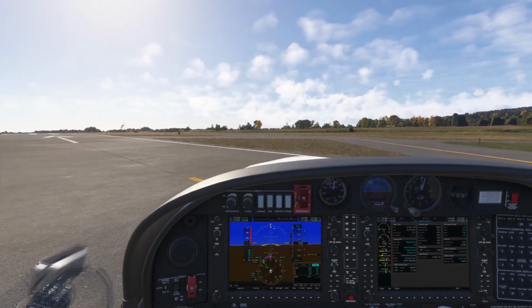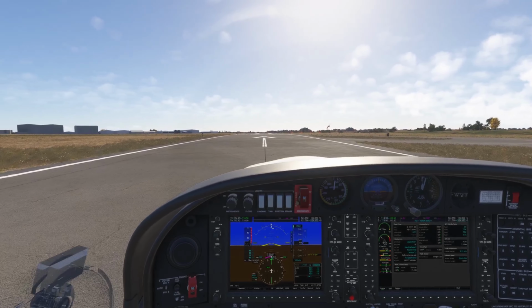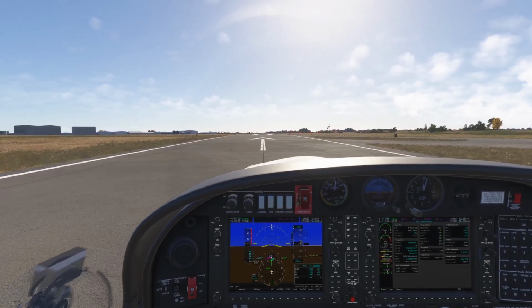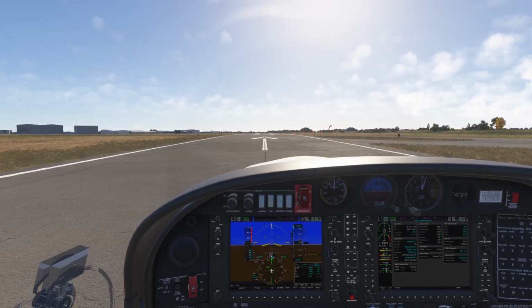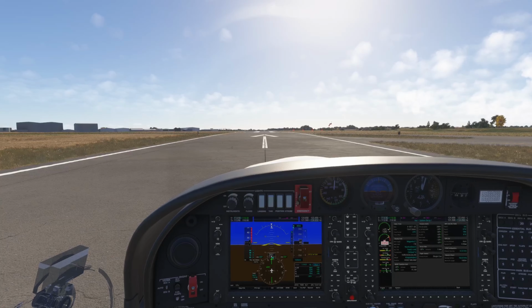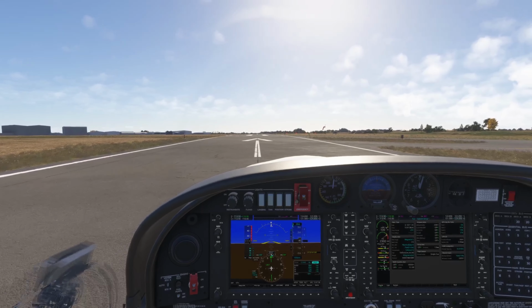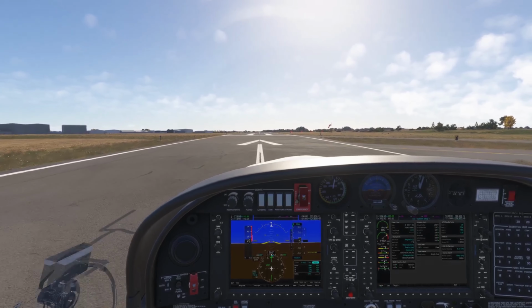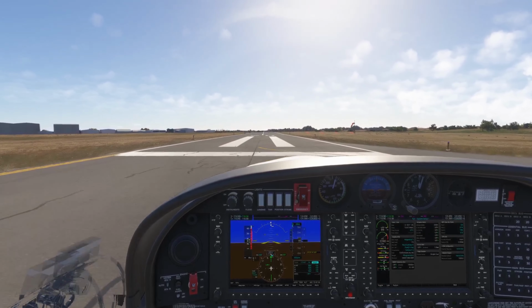Okay, so wind's coming from the right, so we do right ailerons into wind. There we go. Hold on the brakes, right ailerons into wind. So we set full power whilst holding on the brakes, because this is the power jack, 100%, T's and P's holding in the green, brakes released. Okie dokie, so airspeed is building, RPM is set, T's and P's in the green.